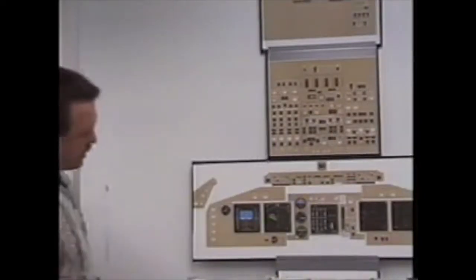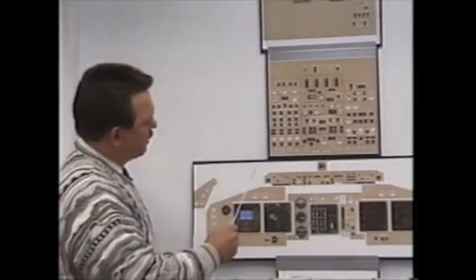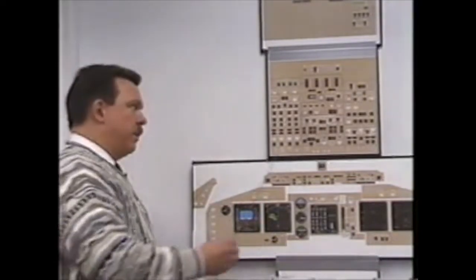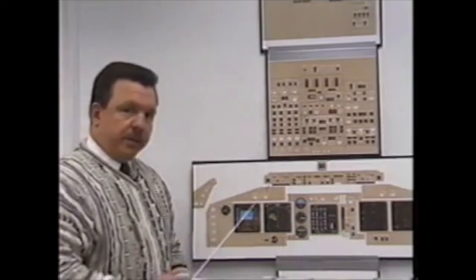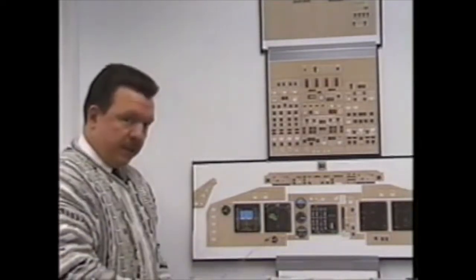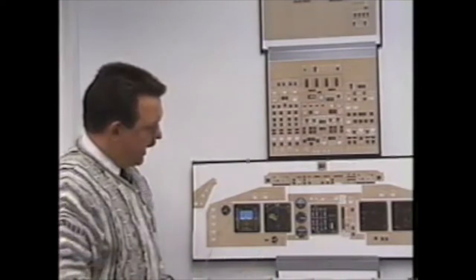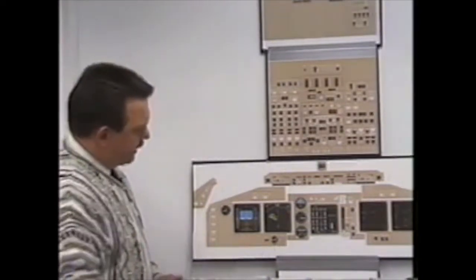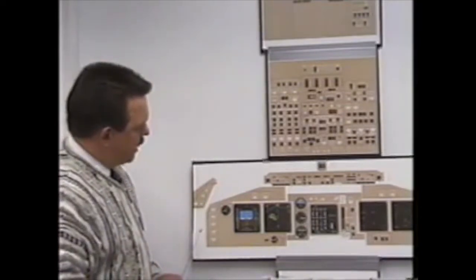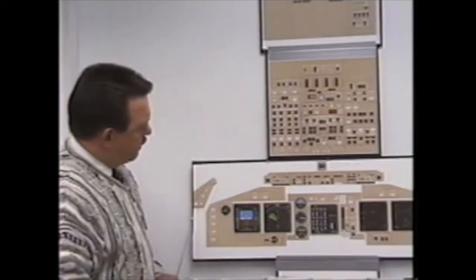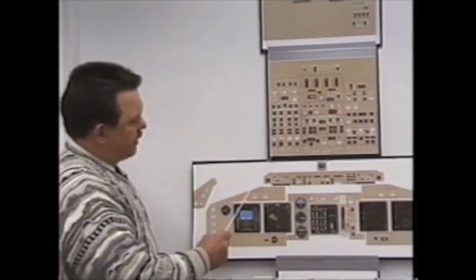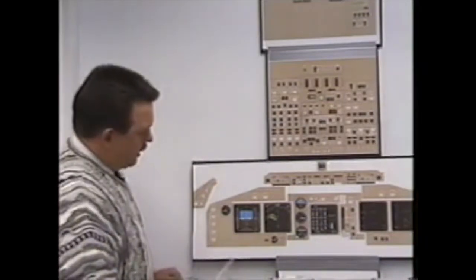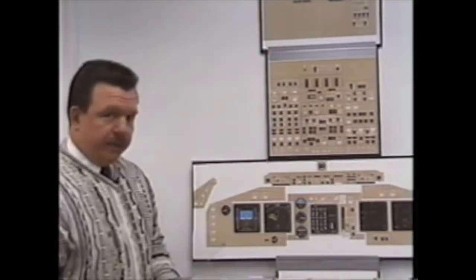Further discussion on your brake system with reference to your hydraulic control panel on the overhead panel, your normal brake accumulator, and your brake source light. We'll simulate that all 4 hydraulic systems are depressurized, and as a result, the brake source light will be illuminated. Your brake accumulator indicates pre-charge pressure. The number here is 750. Brake source light is illuminated, and I reach up and pressurize System 2 hydraulics with the air demand pump. System 2 is pressurized. That will not bring up the brake accumulator gauge.